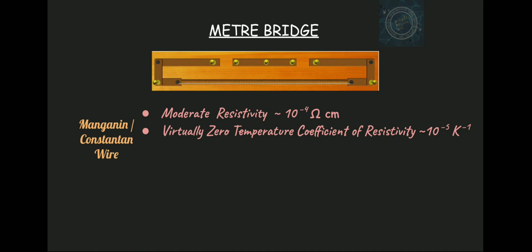It's very simple. If you remember from your school knowledge, the resistivity of conductors is said to increase linearly with temperature. How? Well, rho equals rho 0 times (1 plus alpha T), where rho 0 is the resistivity at a reference temperature, and with increasing temperature, alpha, which is the temperature coefficient of resistivity, a constant, adds a term to the resistivity. So rho at any temperature is equal to rho 0 (1 plus alpha times the temperature change).